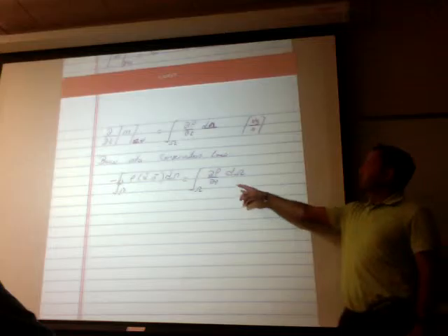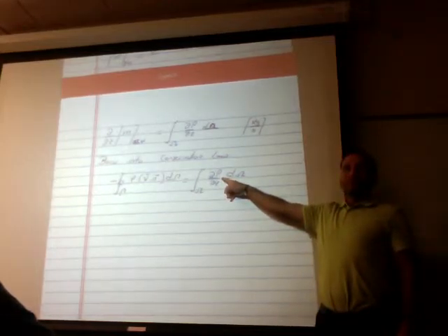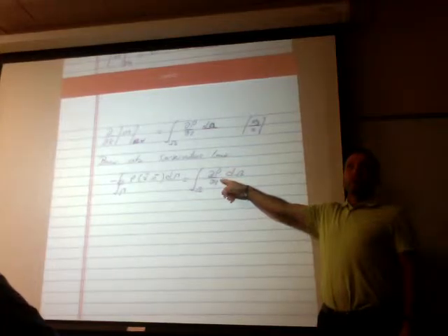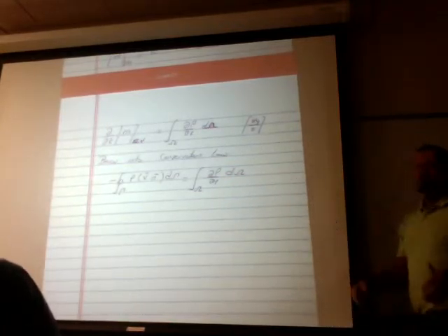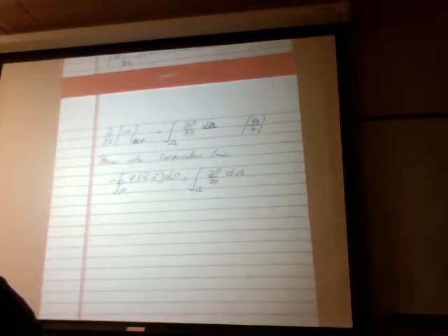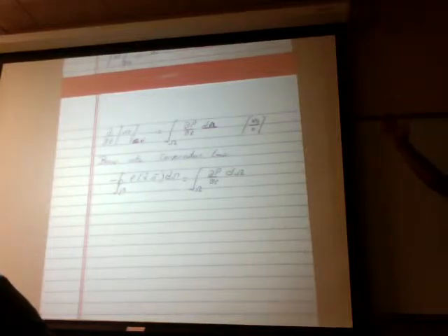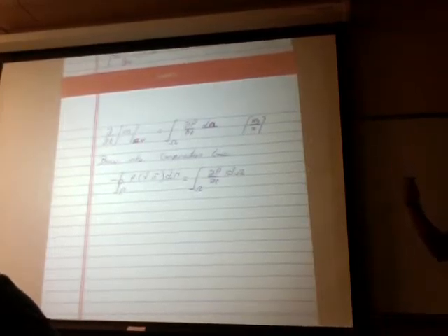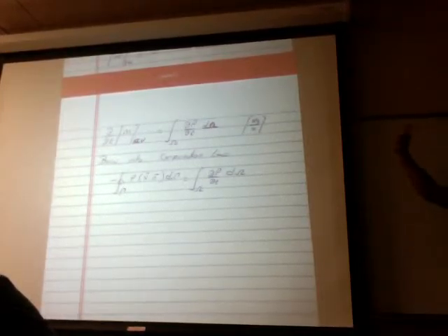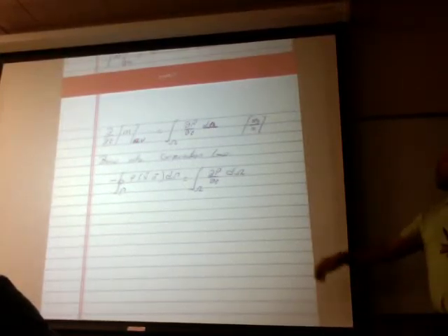So the only way for mass to accumulate inside the control volume, if you're pushing a fluid flow through it, is if the density changes over time, right? If we're talking about an incompressible fluid, like water, you pass that water through that control volume, and you're not going to have any mass accumulation because whatever you put in is going to go out instantaneously on the other side. You have to have an inlet and an outlet somewhere. If you're putting mass in, it has to go out instantaneously on the other side.